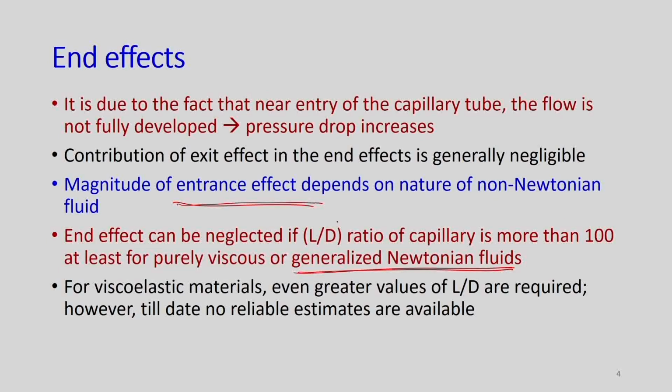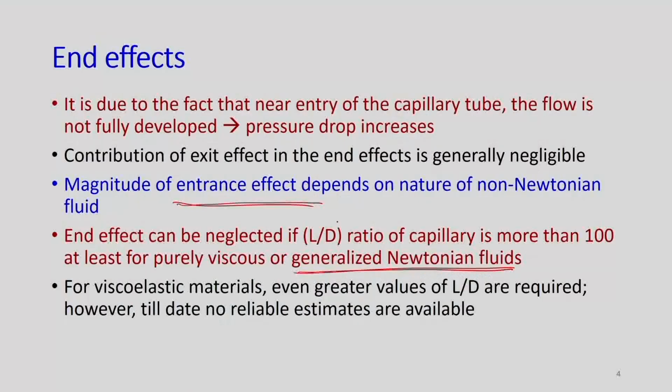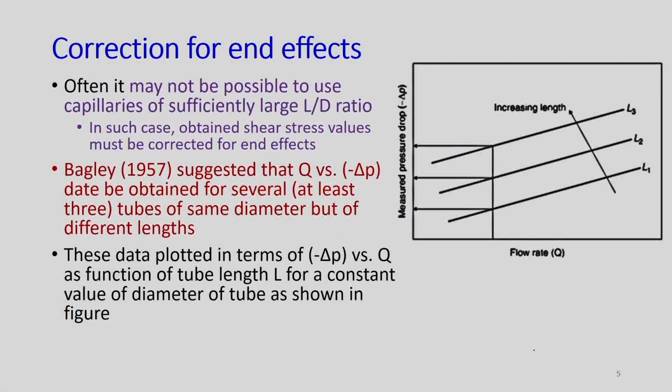However, analogous information is not available for viscoelastic fluids. For viscoelastic fluids, how much the value of L by D should be is not clear, but it is believed that the L by D value would be much higher than 100. So, next, how to make a correction for these end effects.